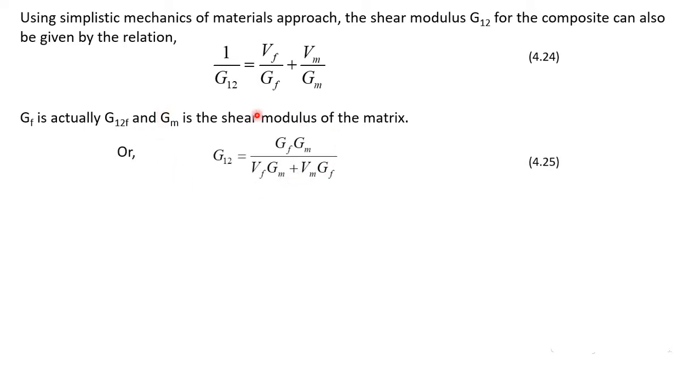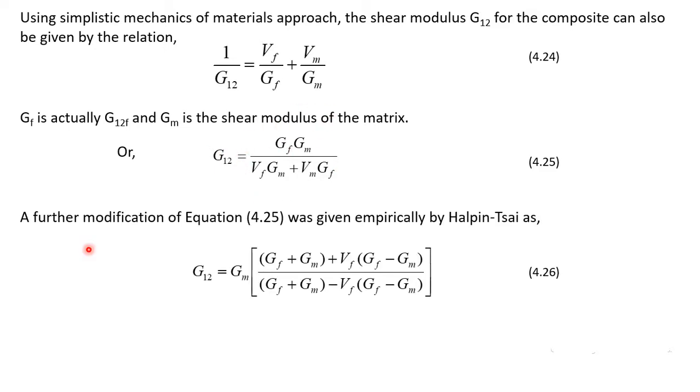Finally, similar to the Young's modulus equation, we can give the shear modulus equation G12 as this one. A further modification of equation 4.25 was given by Halpin-Tsai as this one. Again, if we want to calculate the shear modulus of the composite for transverse loading, then we can use this relation to find the shear modulus.